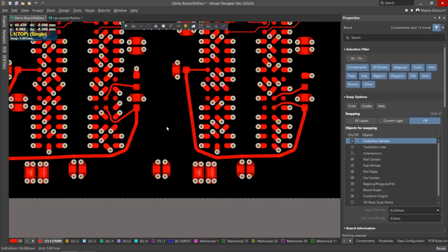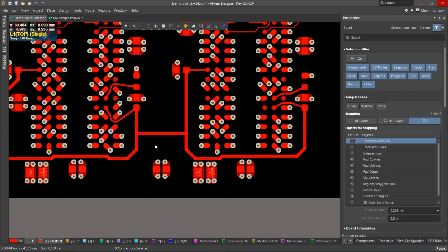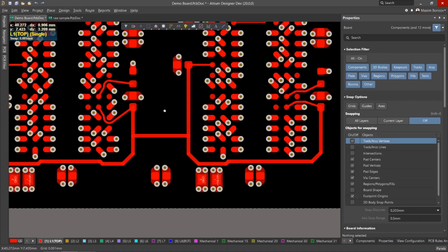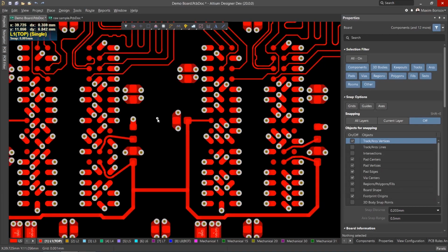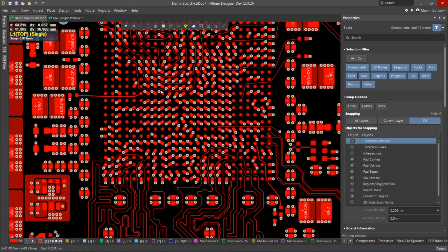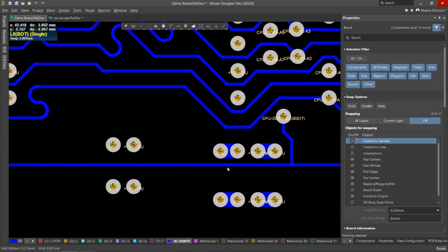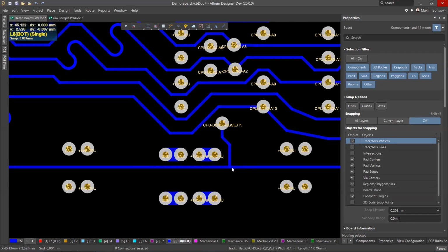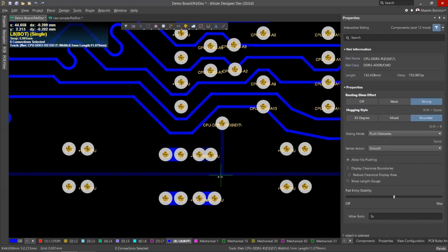So these are quite high performance functions, and I'll tell you later, better say I'll show you a bit later, what means the speed when you're working with large objects, like, you know, this BGA. There is also opportunity to select T-junctions and also push traces.